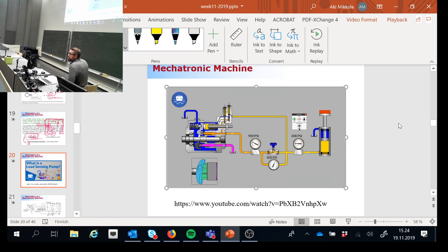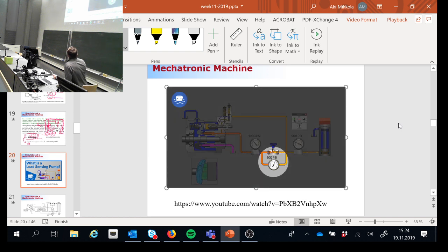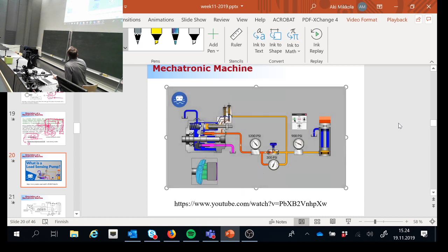What we're finding out is that we're always maintaining a 300 psi pressure differential, sometimes referred to as a 300 psi margin pressure when we're referring to load sense systems. Let's add one more brick, and this time watch the delta P gauge. The delta P gauge fluctuates for a brief fraction of a second, but quickly we find it returns to 300 psi, and we never really noticed any change in speed at the cylinder.